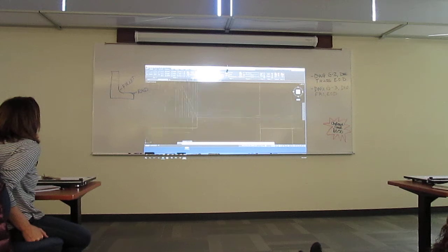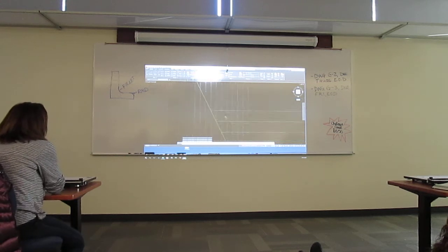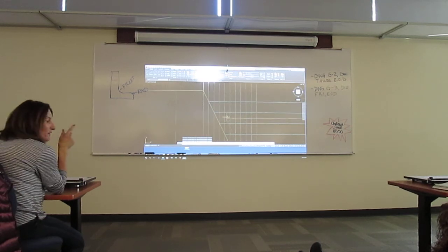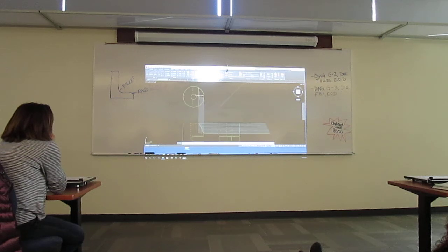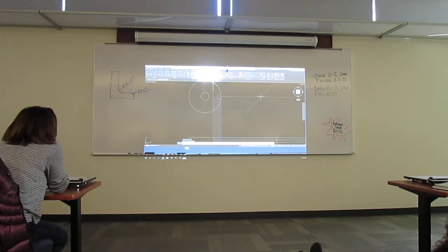Okay, so I'm just going to copy this then from here, and you want to make sure you're getting good snaps when you do this stuff. Okay. So now I've taken all those points and I've transmitted them this way. I know the points fall on this line, I just don't know where. Well, yes I do, it's up here. So I'm going to take this point, I'm going to project it to my miter. Okay, it sits there. Let me drag that out just a little further so I can get a good intersection, because I want to use the copy command on this. So again, I'm just